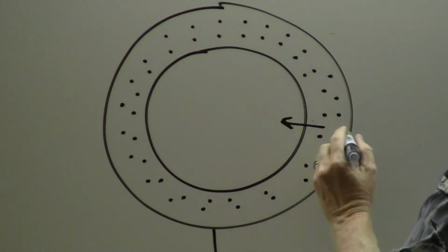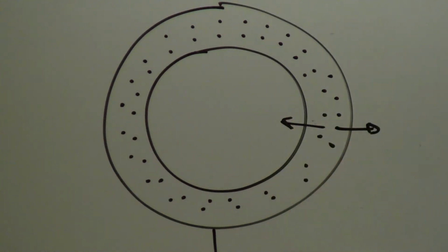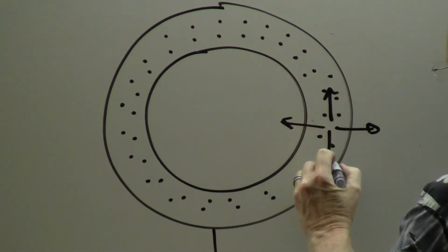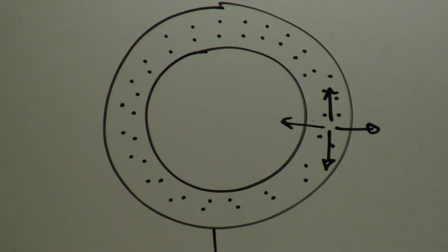They do this. They said, oh, okay, well, if you heat it up, doesn't that mean that the metal will expand like this? It'll expand inward and it will expand outward. And although that's true, if you stop there, you're going to think that the hole in the ring gets smaller, because there's also this going on. They bounce and make the circumference longer also.